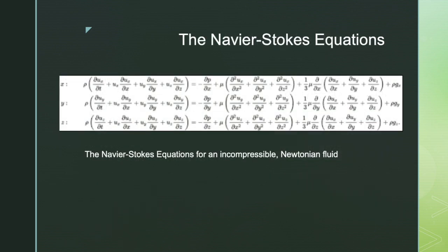The general form of the Navier-Stokes equations needs to be narrowed down using assumptions and limiting conditions in order for them to be useful. This is done by applying the conditions to the appropriate terms of the equation and simplifying. There are several types of assumption that influence the structure of the equations. Some of these conditions are whether or not you are considering a Newtonian versus a non-Newtonian fluid, compressible or incompressible fluid, or even viscous versus non-viscous flow. All of these conditions depend on the working fluid and influence the structure of the final set of equations.